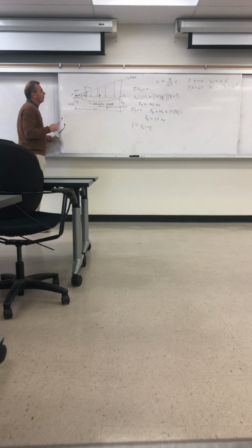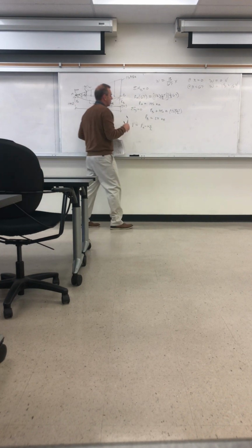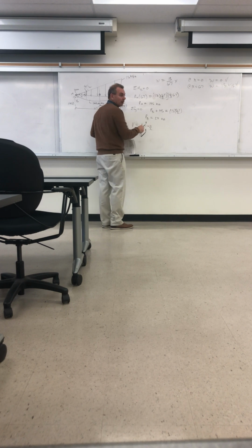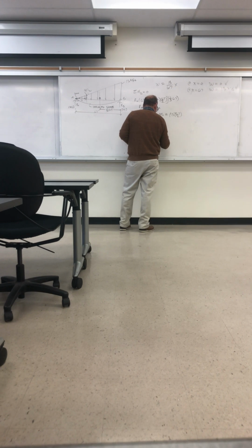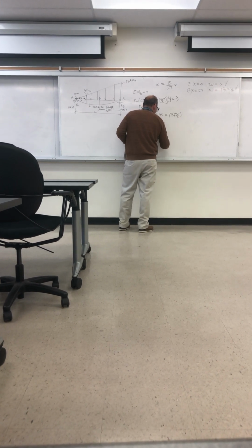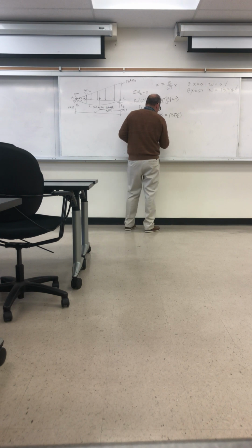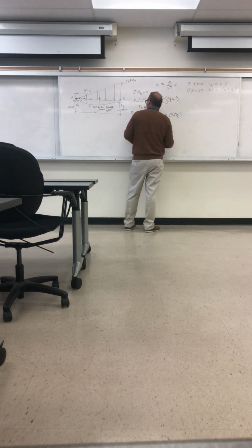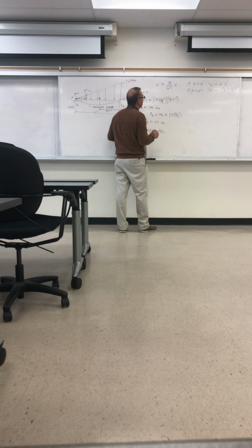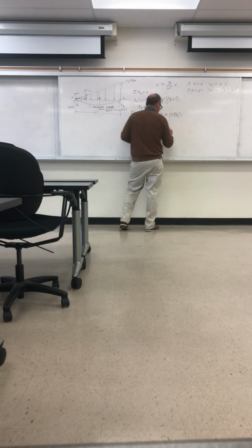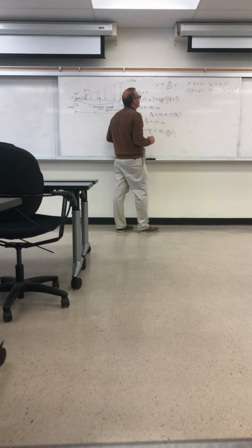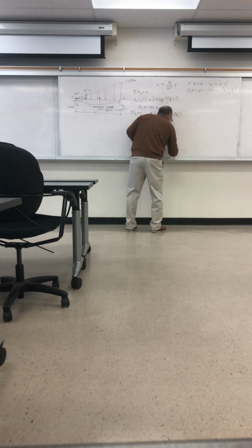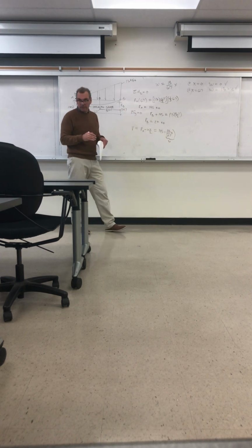So this is the right expression for the distributed load, and then that W is this W, right? So this is equal to reaction A. Okay, I'll put in what the reaction A is then. It's 145 minus W. W is what's varying. 13 over 67 times x. That's W at any given location along the length.